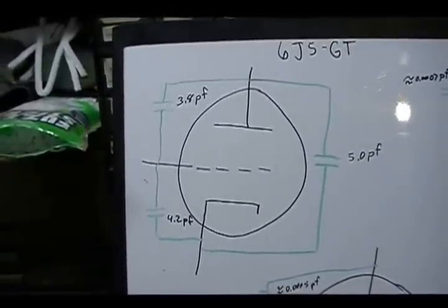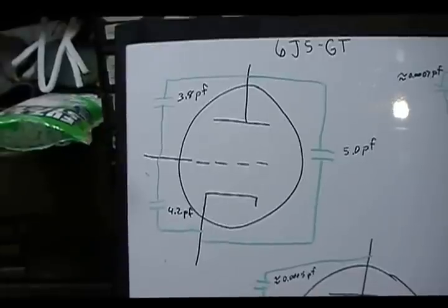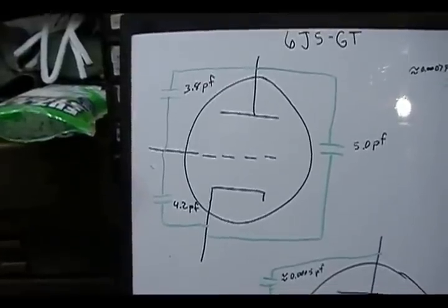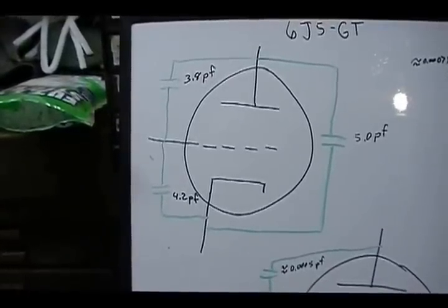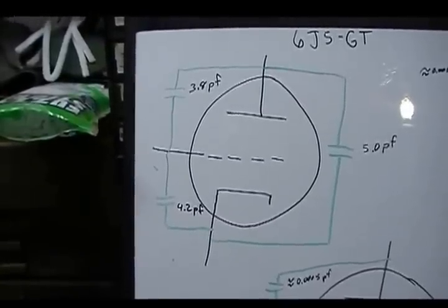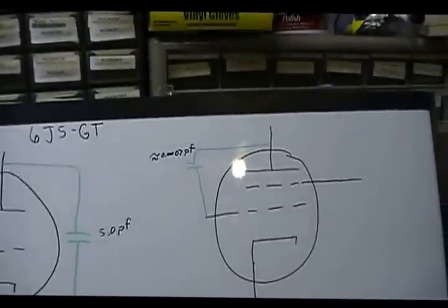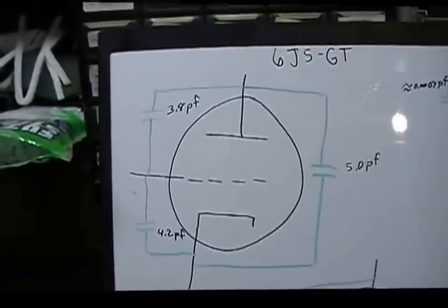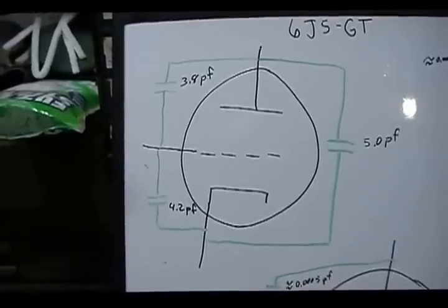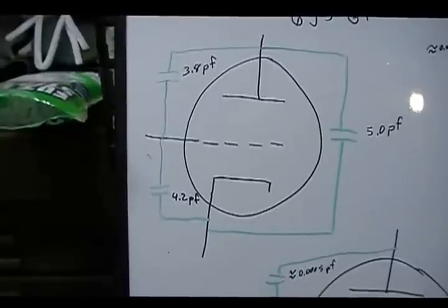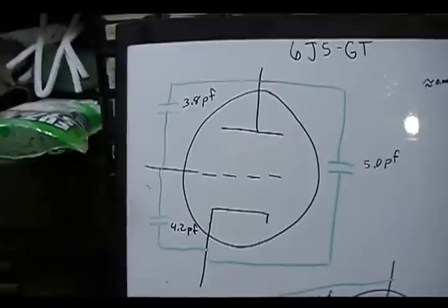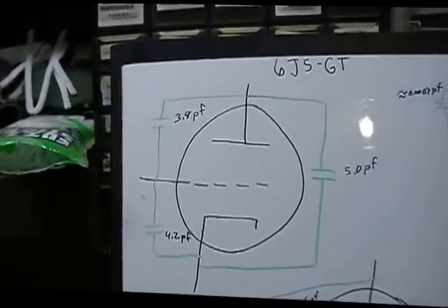Some of the somewhat disadvantages, I'll talk about 2 minor ones which kind of go hand in hand. One is the mu on a triode is relatively low. Compared to these other 2 tubes, it is fairly low. They come in roughly 3 different varieties: low mu, medium mu, and high mu. Well, high mu tubes top out around 100 or just a little over 100 for mu.